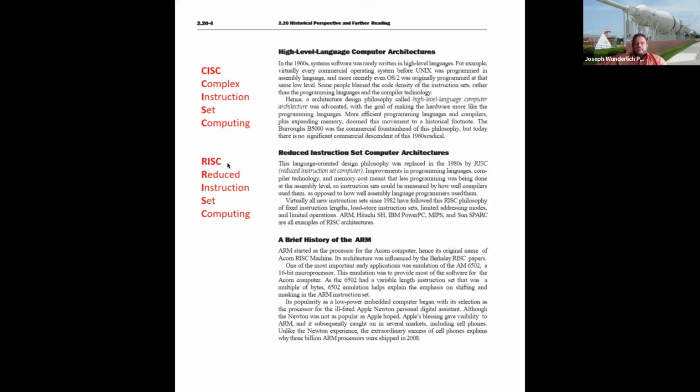Those fields were variable depending on the instruction, and the actual length of the whole instruction was variable too. It's faster to have fixed fields in your instructions for decoding. The machine can immediately go fetch the operand as soon as it sees the opcode and knows right where the opcode is going to be. It's a fixed set of bits.